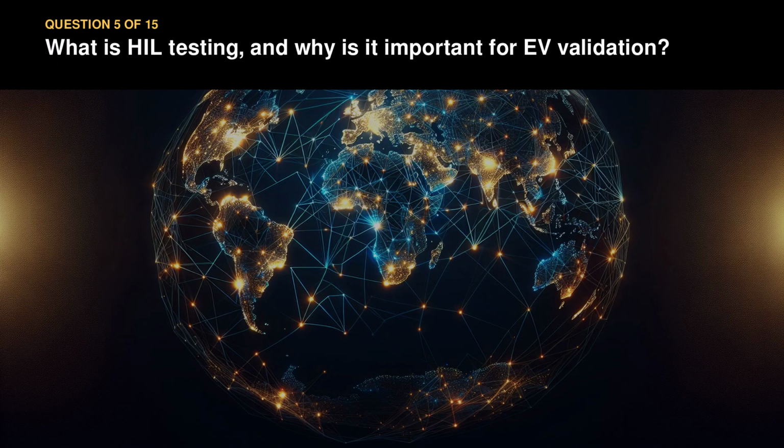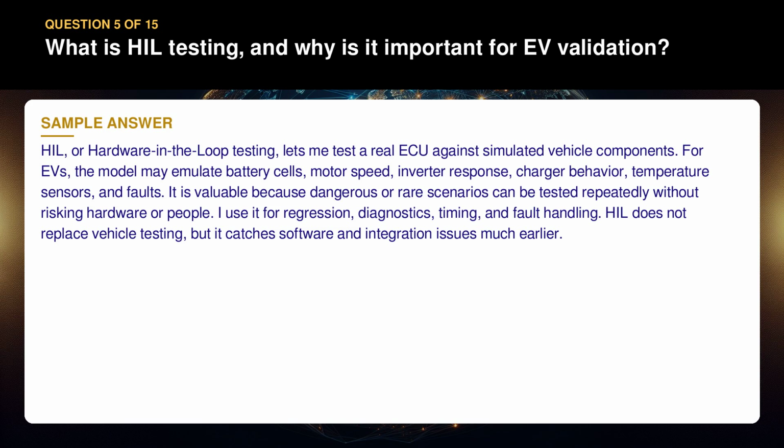Question 5. What is HIL testing, and why is it important for EV validation? HIL, or hardware-in-the-loop testing, lets me test a real ECU against simulated vehicle components. For EVs, the model may emulate battery cells, motor speed, inverter response, charger behavior, temperature sensors, and faults.